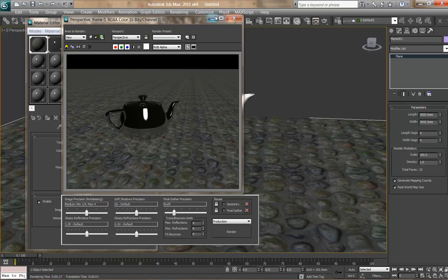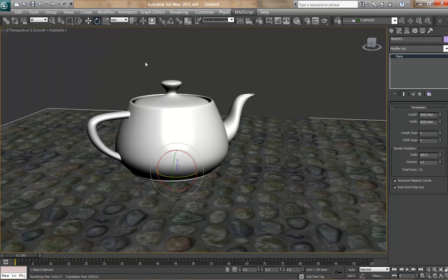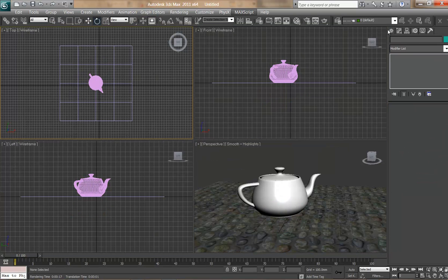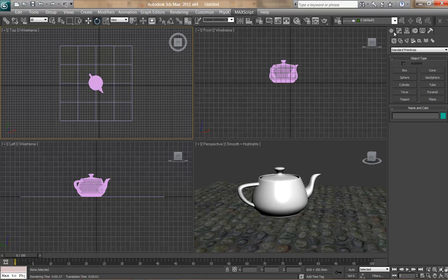And you'll see when you start doing it in 3D software why it's just so much better doing it this way. So now, the one exception is maybe daylight systems. If you import them from Revit, it's as though they've been made in the 3D software anyway. So don't worry if you've got a daylight system. I'm going to make one now. But if you've got one that's been imported from Revit, just use it. They're perfect, and they give you a lot of handy settings.